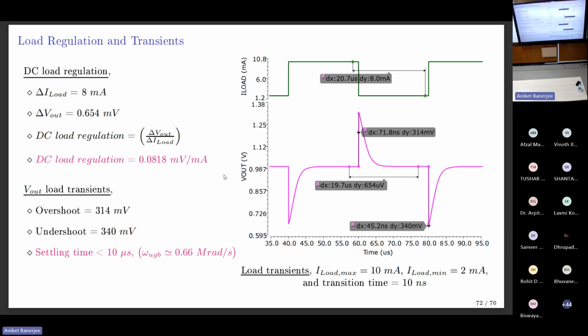I think if your noise parameter is LDO Vout noise, you want some peak-to-peak number or RMS number, or even the spectrum.